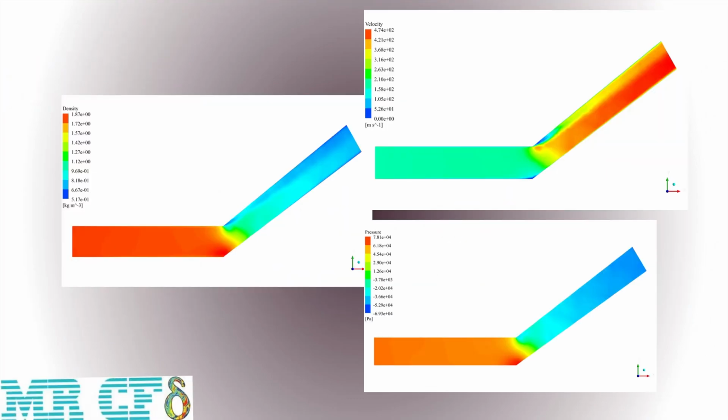Air enters from the pipe inlet with 0.9 Mach number and 5 Celsius temperature. The fluid experiences an extreme pressure drop at the bending zone. The mentioned phenomenon is known as a shock wave and requires a high quality mesh grid to be simulated. The K-omega SST viscous model was used to capture fluid behavior perfectly, especially near the walls.